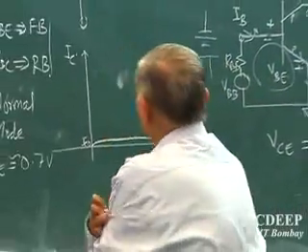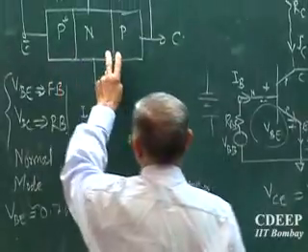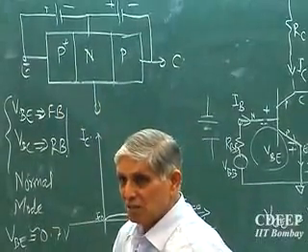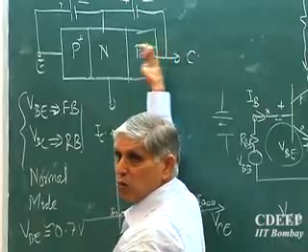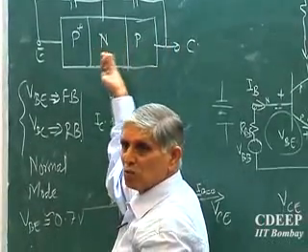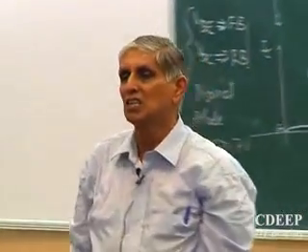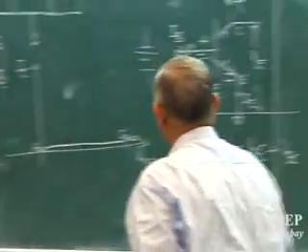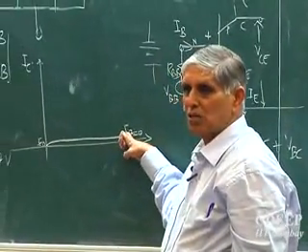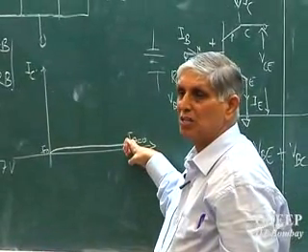This can also be said to be, if this is reverse biased and this is reverse biased, no holes are injected. Minority electrons and holes can do, which is the reverse current of the two junctions, and whichever is smaller, that will flow. Okay. In a circuit, there cannot be two currents. Whichever junction gives lower current, that will be the net current coming out. Is that correct? Now if that is so, this is a very small current. The device is said to be in switch off mode.